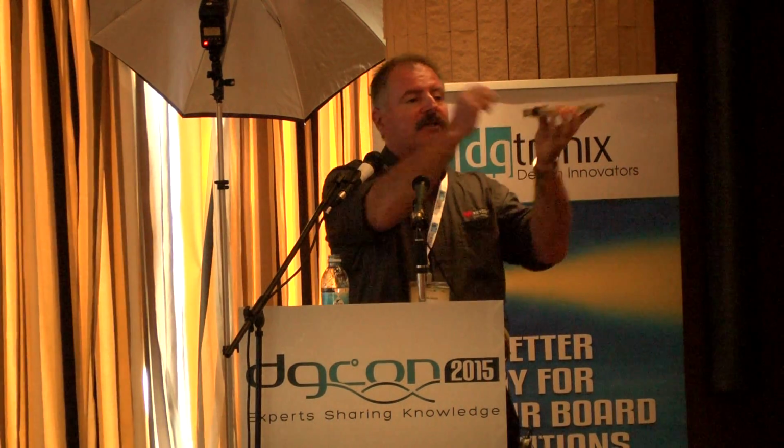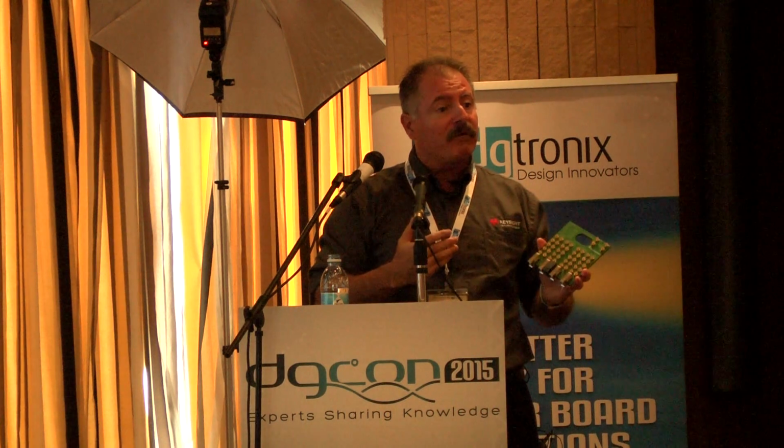So let's think about that for a moment. The idea now is I don't even really need to build a 2x through anymore. I can take the fixture and I can pull it out and I can use the open circuit here as the open. So I don't need to measure a through. I don't need to pull this connector off and probe it, nothing like that. So it's just a reflect measurement, which is quite easy.